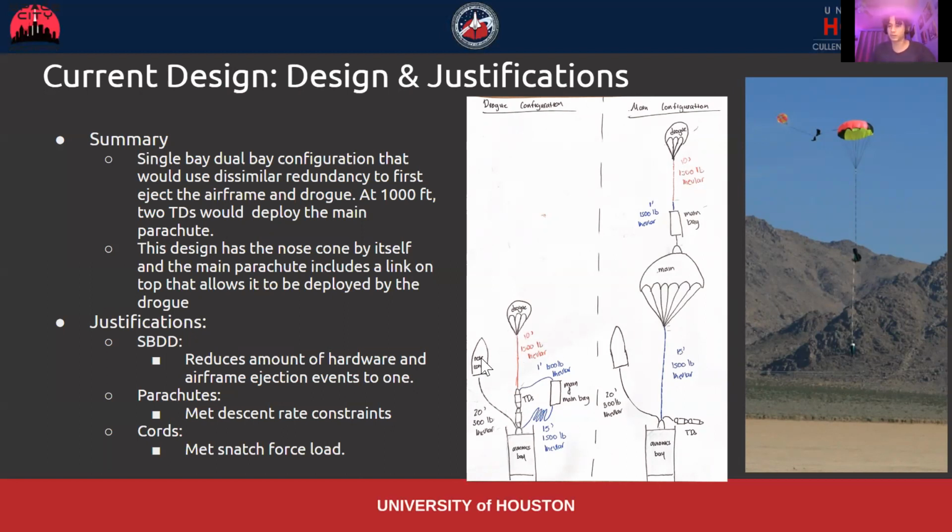And Randy's justification for doing this is that having this here is still a lesser risk than having the nose cone and the drogue the way we did, where you run into the possibility of everything getting tangled when the main deploys. By doing this, you eliminate that completely.